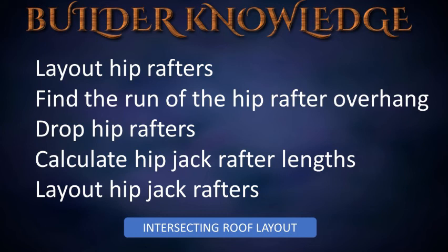Mark the angles for side cuts, ensuring the angles intersect the square and center point lines. Draw the ridge plumb line using the unit rise on the square tongue and the number 17 unit rise on the square blade. For a speed square, place the pivot point along the rafter edge and rotate it until the desired unit rise and the hip valley scale align with the rafter edge.